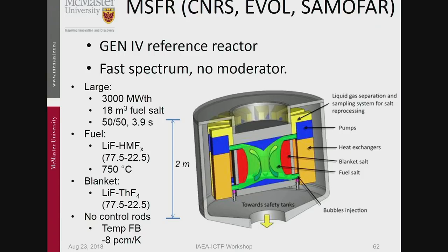So the temperature will go up in the reactor. If the temperature in the reactor goes up, the reactor power goes down, and that means that power goes down just like the load goes down. So the power in the reactor follows the load. It happens automatically. You don't have to do anything, theoretically.